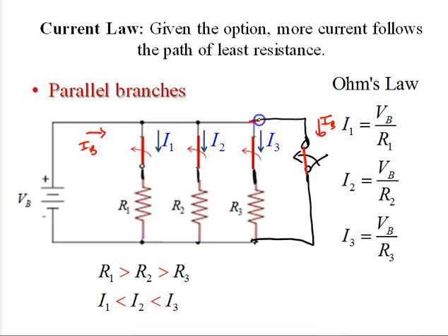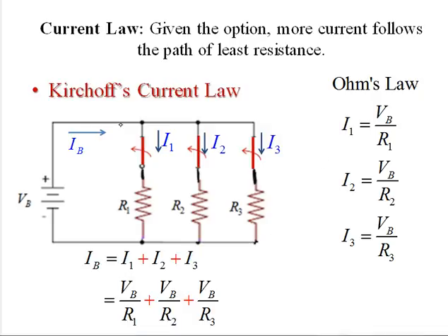And this is what we don't want to do in lab by mistakenly shorting something out. Since the resistance is 0, IB is going to approach infinity, or it's going to do things like burn things out, get things to melt.